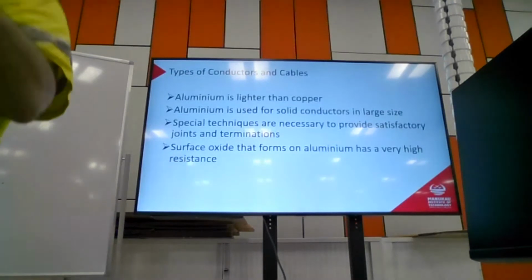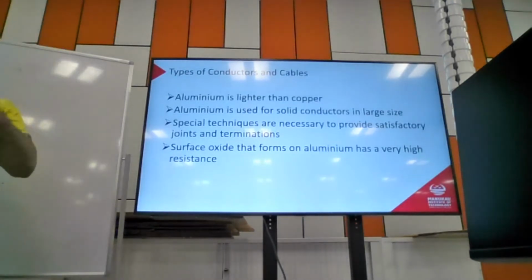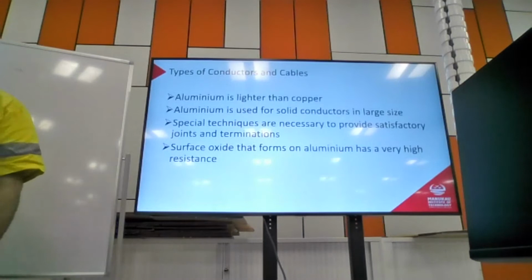Yeah, it makes aluminium really hard to weld because obviously you're trying to join two pieces together, and if they don't melt consistently or easily, then it's not going to work very well. So when you're welding aluminium, you've got to file where you want the joint, and then usually put a chemical on it to stop the oxide forming, and then do your welding. It's highly specialized, and people will generally be specially trained just for welding aluminium.